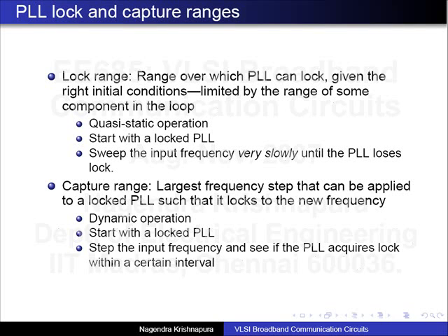Yeah, I'll discuss that. No, lock range is definitely greater, right? So if it is outside the lock range, it simply means that the PLL cannot operate at that frequency. So the capture range just says whether it can do it within a certain time or whether it can do it when a step is applied.